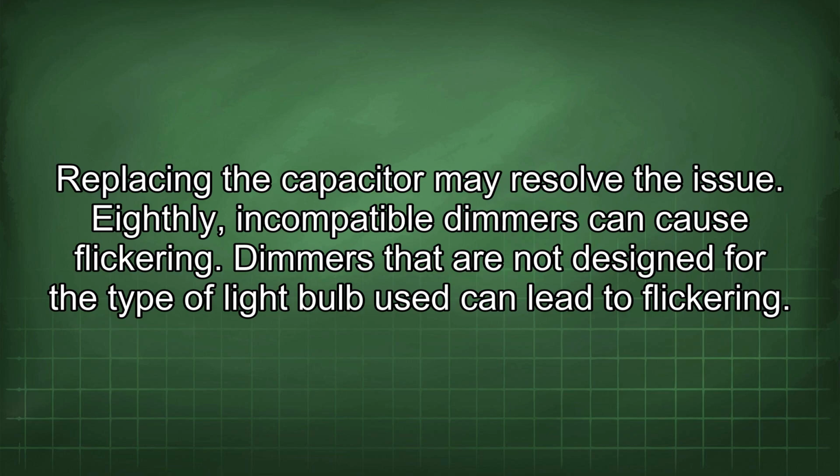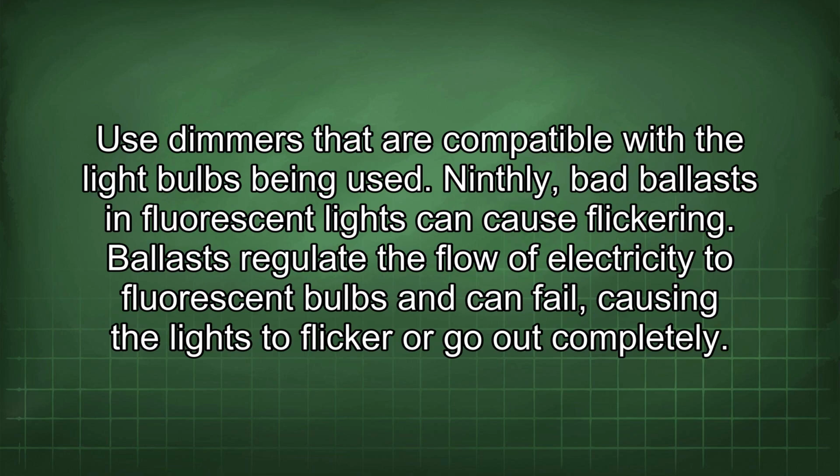Eighthly, incompatible dimmers can cause flickering. Dimmers that are not designed for the type of light bulb used can lead to flickering. Use dimmers that are compatible with the light bulbs being used.